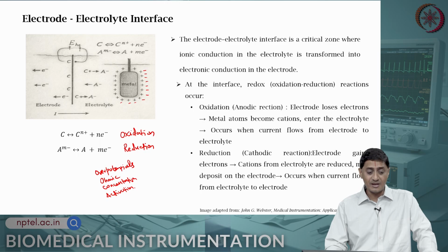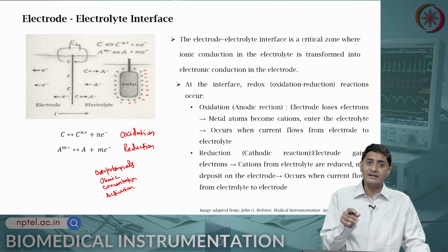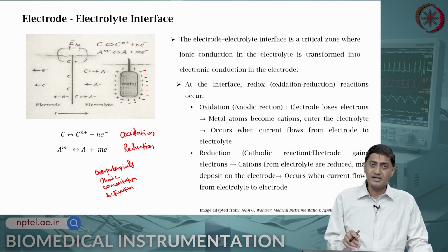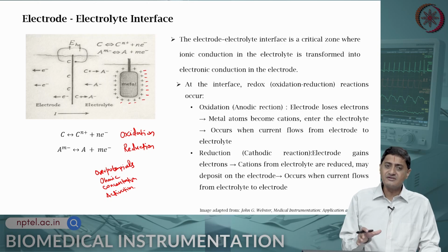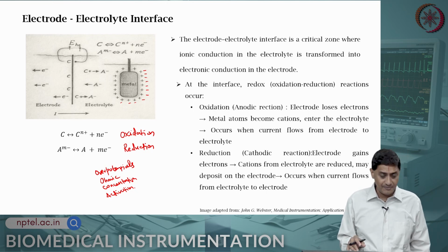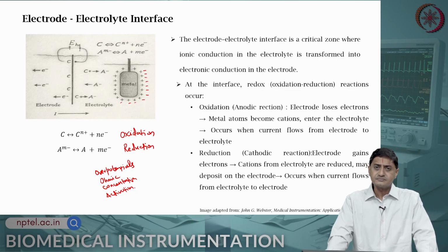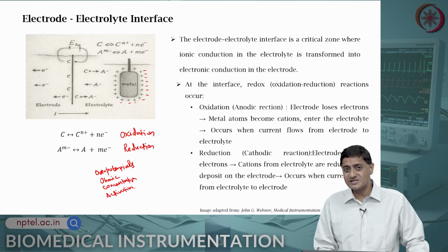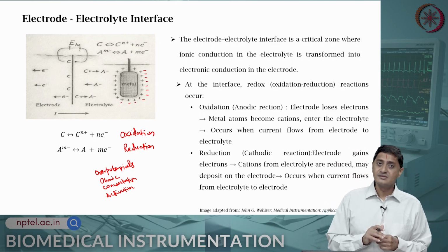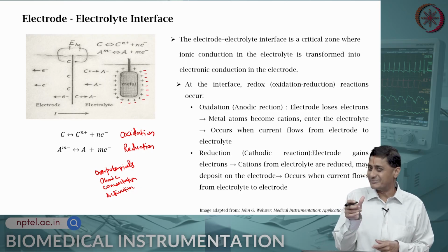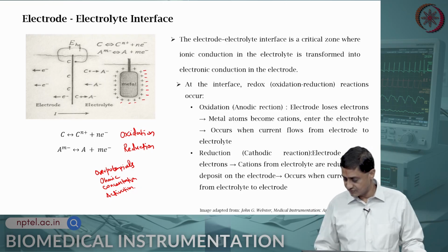So, this is what happens in the electrode electrolyte interface. When you dip a metal into an electrolyte, what is formed is not a trivial oxidation reduction reaction alone, but rather a bilayer, a two layer or a charged double layer that is formed. So, there will also be some capacitive effects. That means that when you say there is a capacitive effect, from our understanding of electronics, you can immediately realize that there is going to be some frequency dependence, something that we will discuss in future videos.